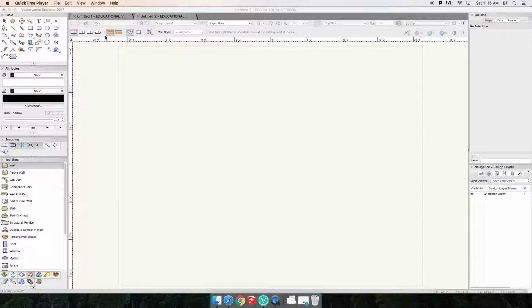So when we are getting into drawing walls, there's going to be multiple components, and when we are drawing it, say if we had specific dimensions, we want to draw so that those dimensions are applicable to the outside of our sheathing. So when we're dimensioning our exterior dimensions, they are to that exterior or outside of sheathing. So we want to make sure that they're referenced in that way.